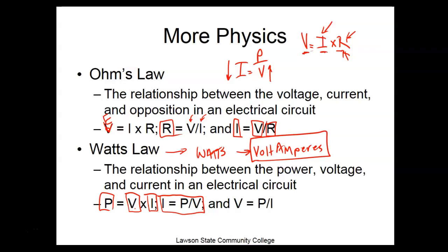If I was going to give you 1,000 watts of power at 1,000 volts, then it would only require 1 amp. So what that means is if we can make the voltage real high, then we'll have less loss in our lines. So what that means is we can step the voltage up and down with these devices called transformers.